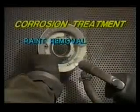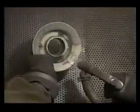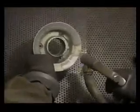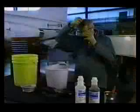Paint removal from small areas is usually accomplished by mechanical abrasion or hand sanding. Chemical paint strippers are used on larger areas and should be handled with caution. Whenever you are working with chemical paint removers, check the label or material safety data sheet for any special manufacturer's instructions you may have to follow. Wear protective goggles and rubber gloves and protect your skin from accidental splashes.